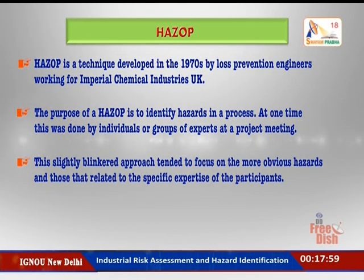of the participants. So in contrast to this, HAZOP involves a deliberately chosen balanced team using a systematic approach. So this method is to systematically brainstorm the entire plant part by part, and to review how deviations from normal design quantities and performance parameters would affect the situation.